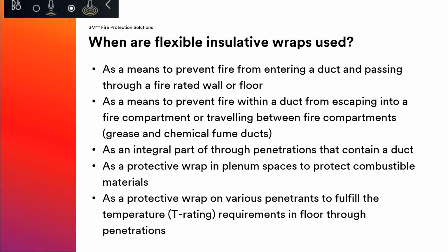Okay, so again, when you have that exposed metal pipe, that's going to transfer heat rapidly and potentially start a fire in a non-fire area, or in an area where there's no fire. We want to insulate that metallic item to slow down that transfer of heat.